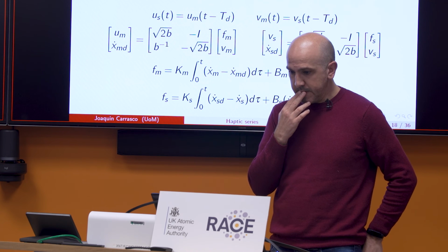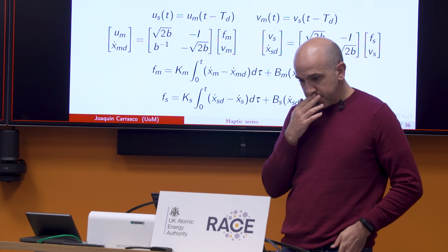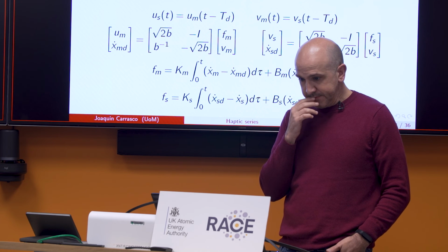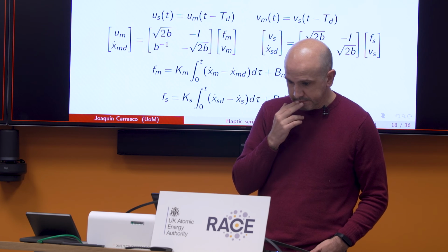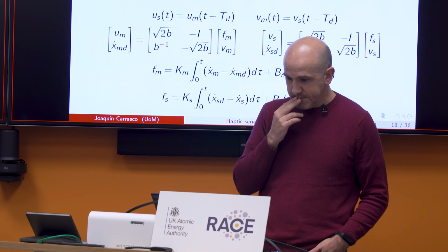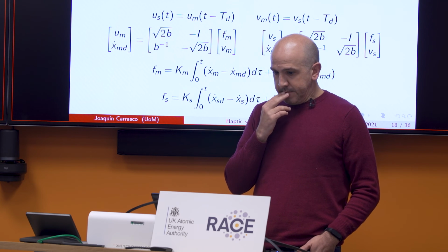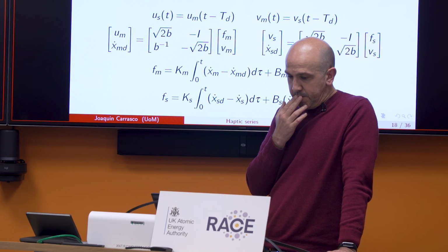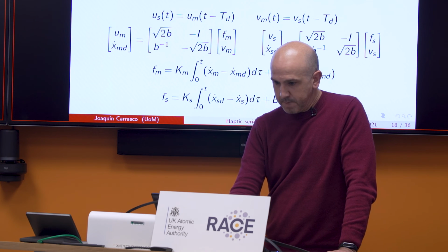Joaquin, may I just point out, I don't know if you mentioned it, but one of the interesting things here is that the product of velocity and force, so you've got x dot, which is the change of position, the product of velocity and force is power. So the combination of these two is the power in and the power out. In other words, the rate of change of energy in the system. This configuration shows the power flow and the accumulation of energy in the system.